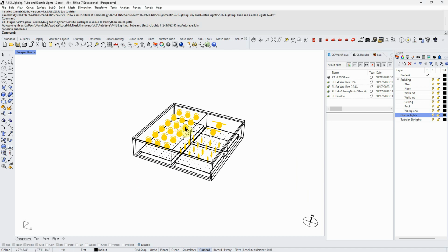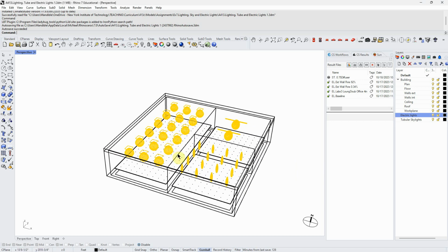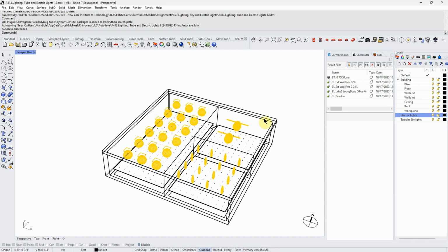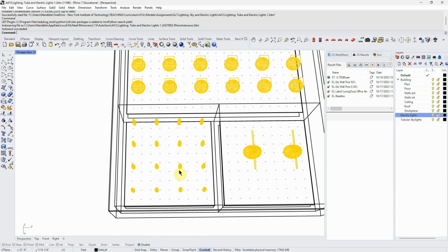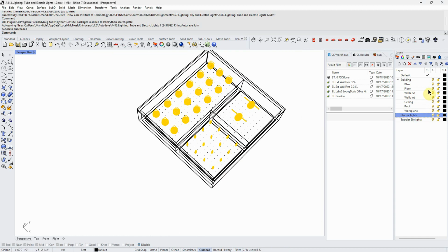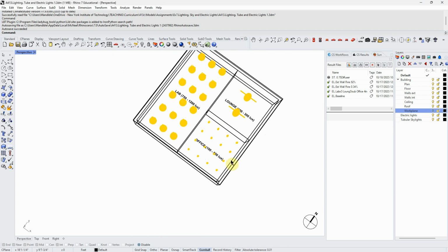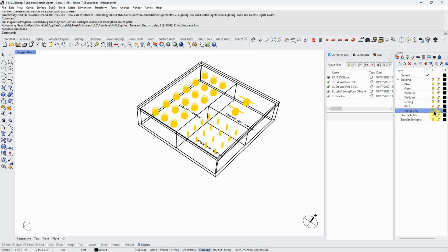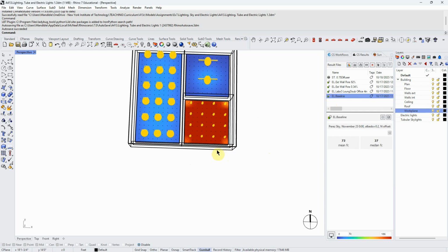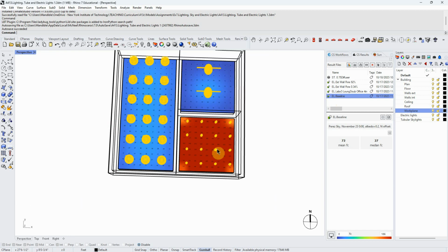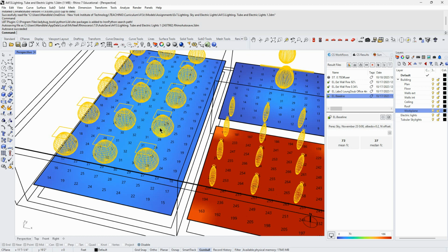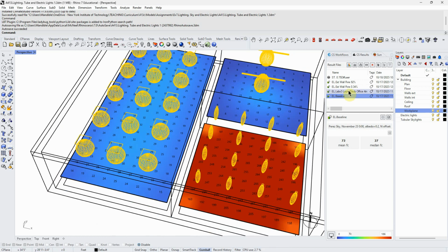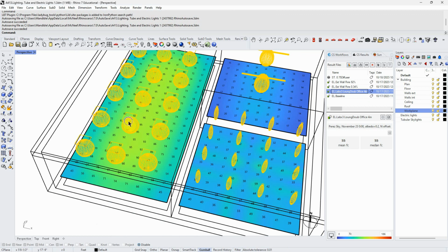And so the last thing I'm going to show you in this context is the same model. I did separate lighting choices for all 3 rooms, because remember, we have these different lux targets. And then, what were my results? I started with a baseline, and then I made adjustments to each light, each different light in each different space. For example, in this one, I just increased the multiplier by 3.